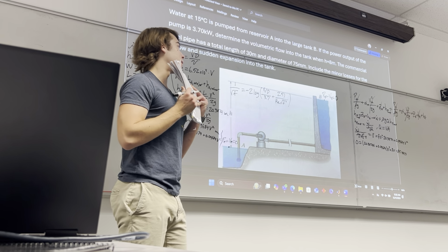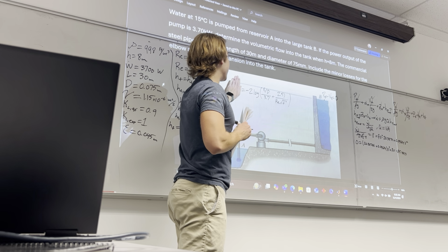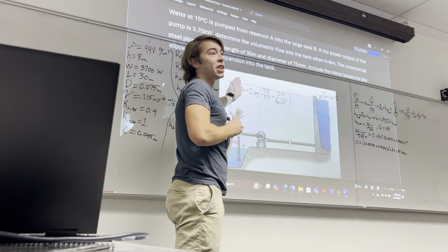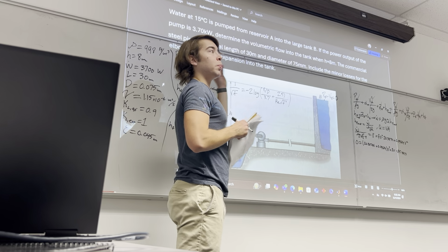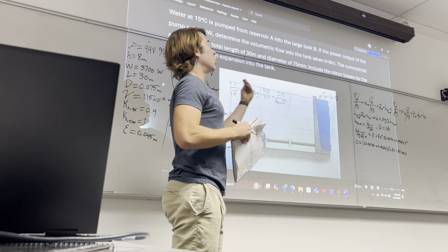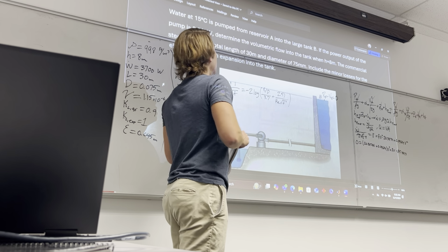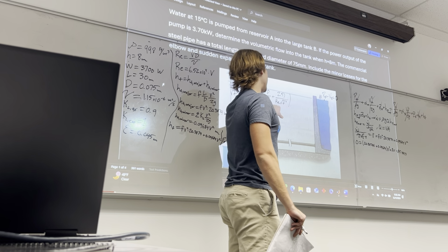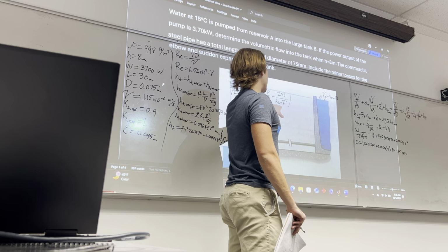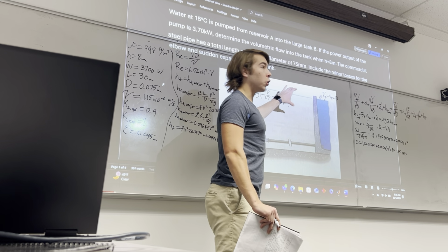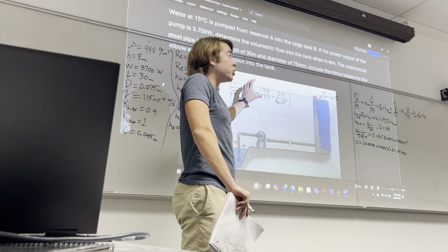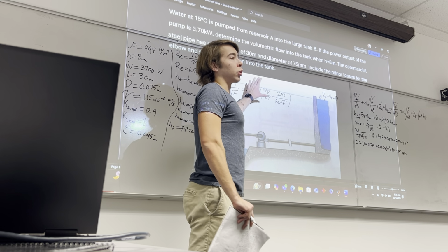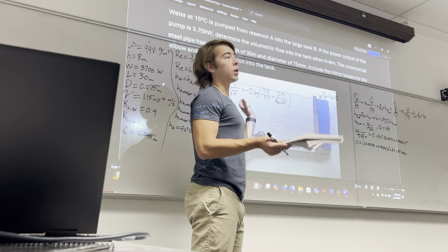What you do is ignore this left side for a second, and then you pick some random f value, literally pluck a number out of thin air. You can pick whatever you want. Plug that in for f, and assume you know a Reynolds number. Solve this right-hand side for that random f value you chose, and let's say this works out to be like 100 or whatever.